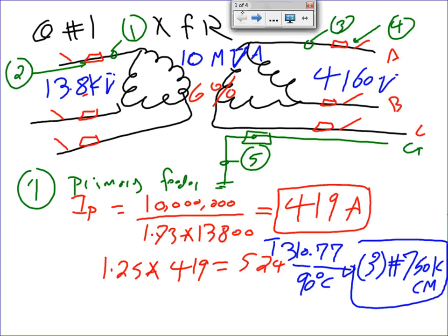A second short circuit on a different phase will bring you down. That's why they use the ungrounded system. And say a squirrel is climbing over here on the pole and lands and shorts to ground, nothing will happen. You don't trip and turn the power off on half of the city of Minneapolis because of a squirrel dancing on the transmission line or distribution line.